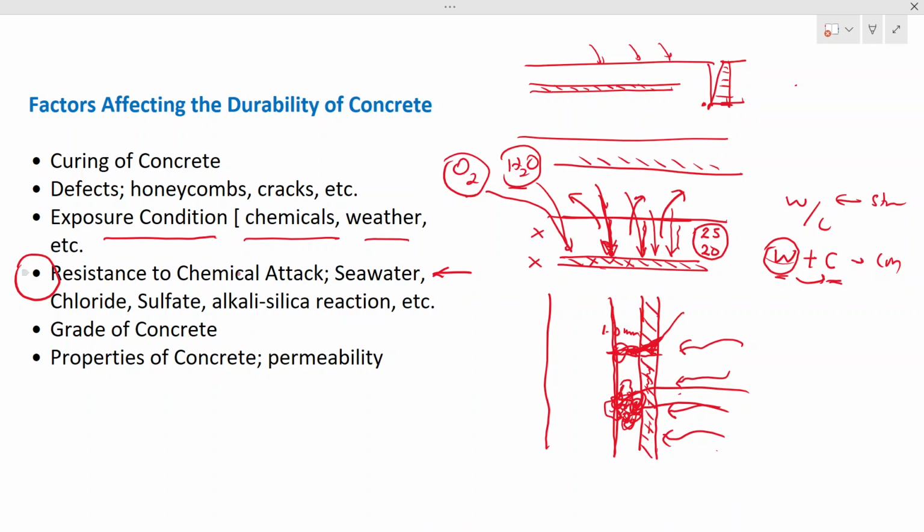One other thing that I want to mention here is the alkali silica reaction. That is actually not directly connected to cement, but it is a reaction of the components in the concrete with the aggregate. So we also have to think about that when we select the aggregate. That's also an important factor. It could create internal and surface cracks, which will affect the durability.